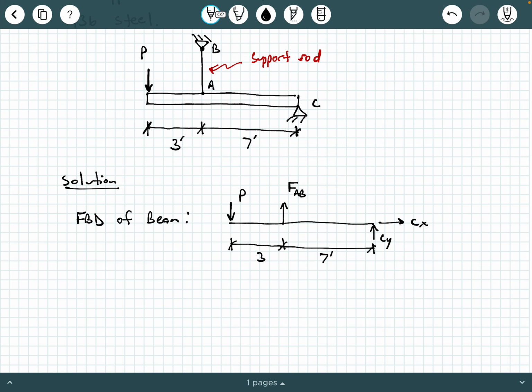So if you remember from statics and physics, a free body diagram of a system is a simple diagram, usually with stick figures, that shows all of your known and unknown forces, moments, and dimension lines. Also, if you remember from statics, whenever you have a simple rod or linkage, you just have an axial force developed in the direction of that rod. That's why FAB in this free body diagram is shown as vertical, and that's all you have there. It's like a simple rod or pin connected linkage, and then over at C is an external pin support, so that's why you have 2 external forces developed.